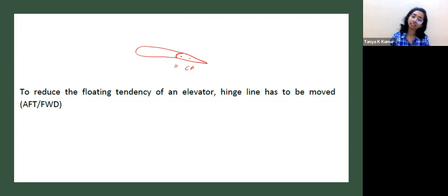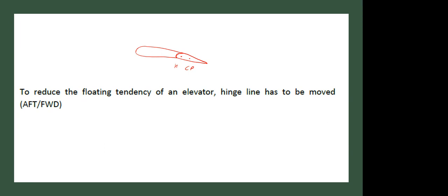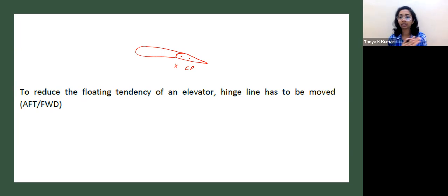We just discussed this. Suppose you want zero floating tendency. What do you do? CP and hinge are at the same point. Yes. So you move your hinge towards CP or you move your CP towards the hinge, right? So that is how you reduce the floating tendency.